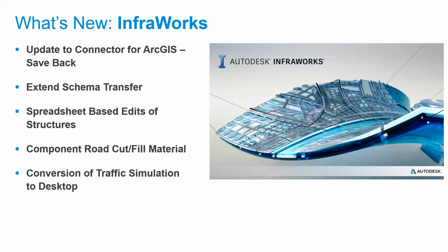But also more important is the spreadsheet-based edits of structures, where this makes it possible for the bridge engineers, those who model bridges, tunnels, and what have you within the Infraworks interface, to export the bridge structure in terms of the model components, that is the sizes, to customize it further within an Excel spreadsheet, after which you can update it back within the Infraworks interface.